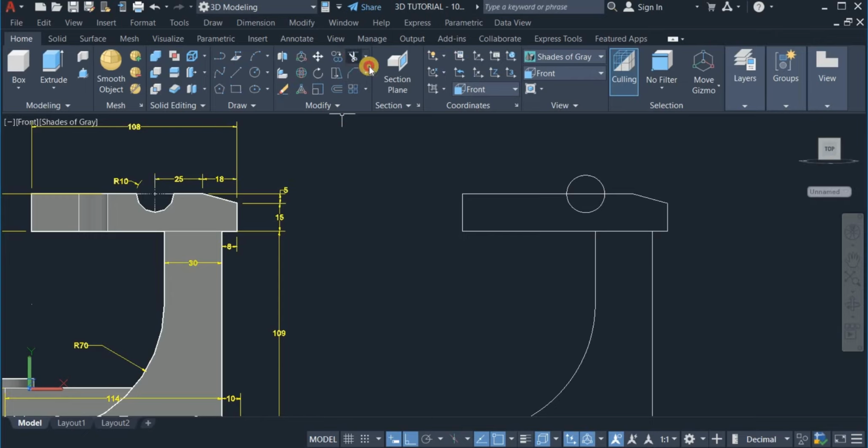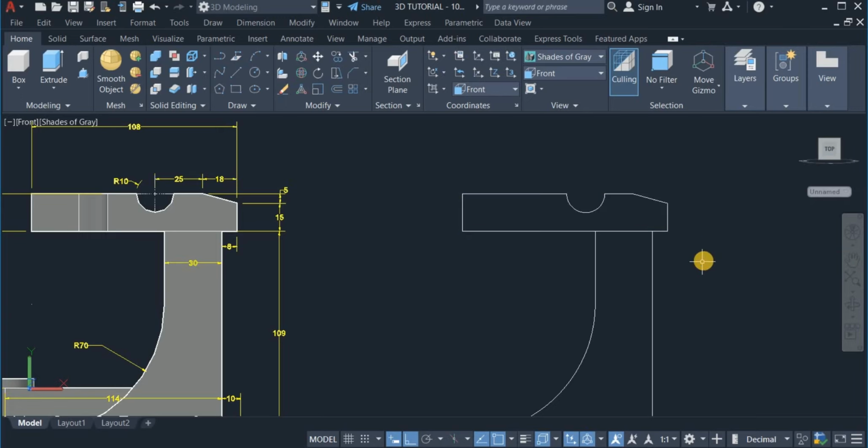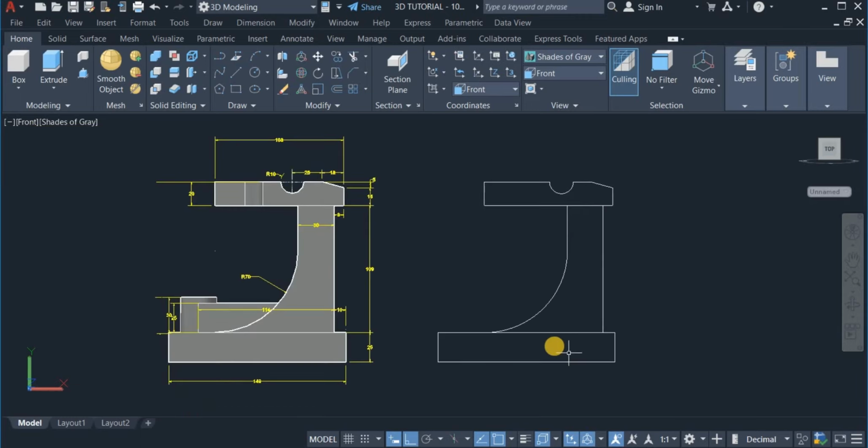Now click on the trim command, trim out this portion. Okay. So here now I'll use the join command to join up all this. So come to the modify panel, click on modify and click on join. Then highlight the whole of this, enter and exit. Right. So I now have 3 different geometry here. That's the first one, the second one, and here is the third one.